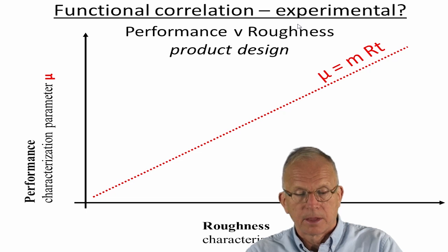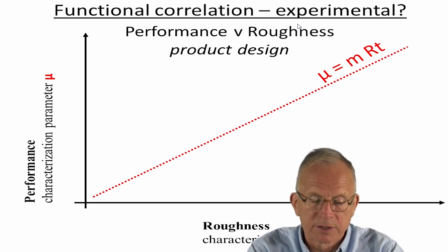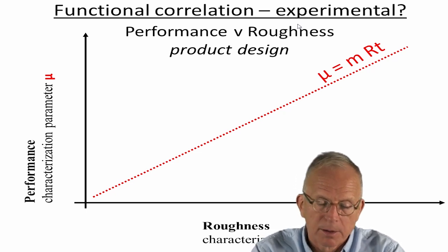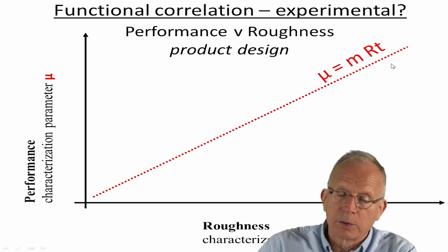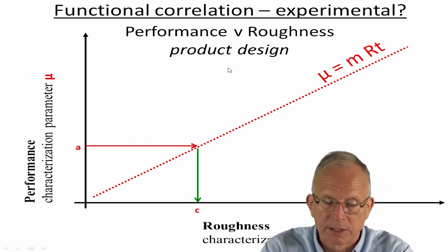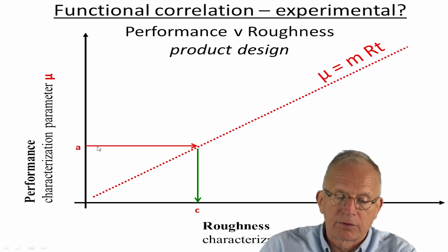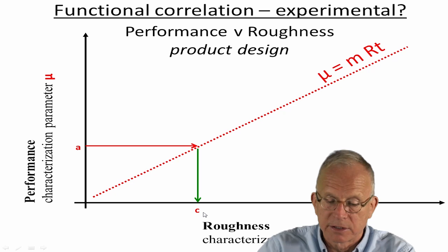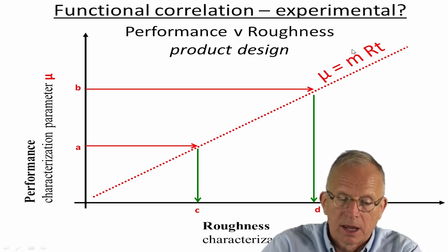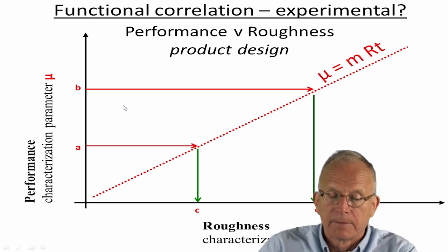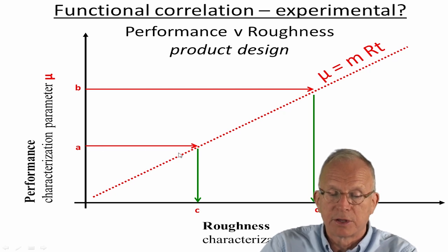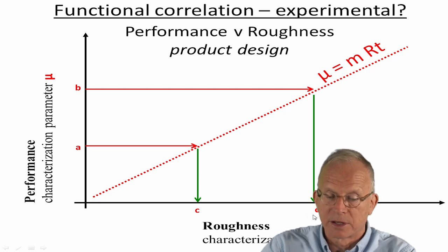We've worked here on the friction of tires and pavements, but in this case we're going to assume this relationship for the point of illustration. So here is friction A for grip, and this corresponds to some roughness, based on this relationship. And here is friction B for slip. As long as the friction coefficient is in this range, we will have sufficient friction so that we don't slip, and we won't have so much that we start to cause injury.